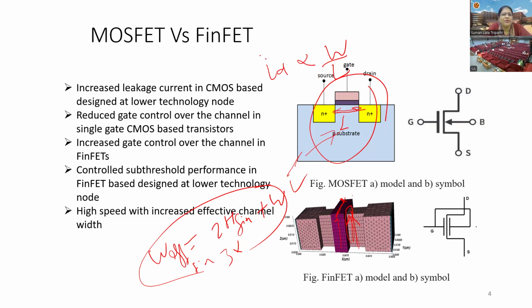It will provide you faster switching. So for different logic applications, and mostly the processors, if we talk about FPGAs, they are based on multiplexers. So to improve the multiplexers' speed, we can use FinFET technologies. And another thing is more gate control over the channel.